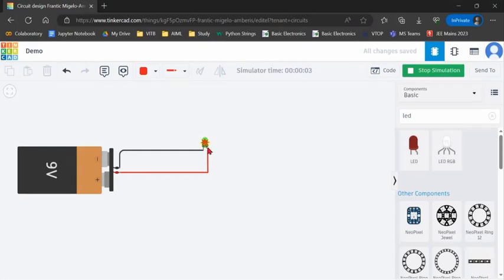But once we go close to here, you can see the current through the LED is 915 milliampere, while the absolute maximum is 20 milliampere. That is saying there is lots of current going through this LED. Only 20 milliampere should be flowing through this LED, but it is 915 milliampere flowing.